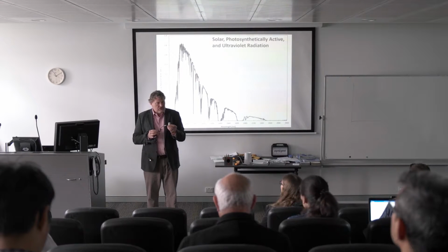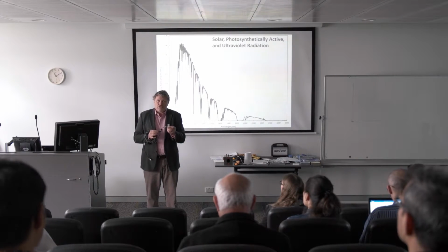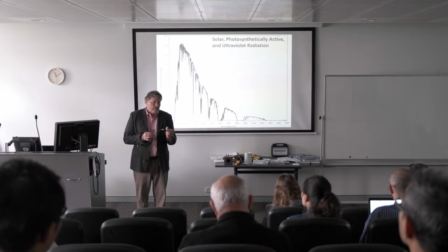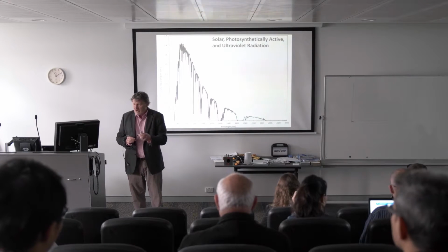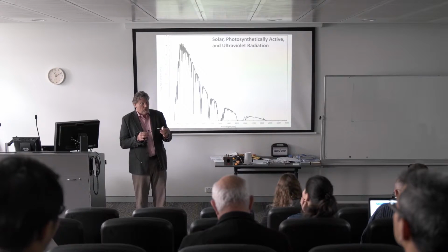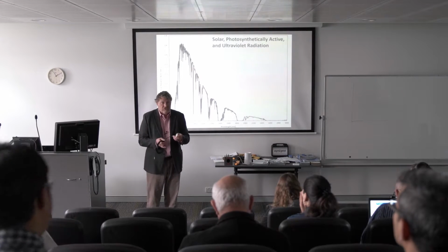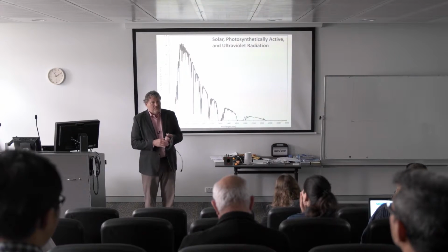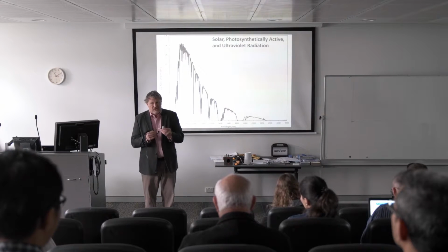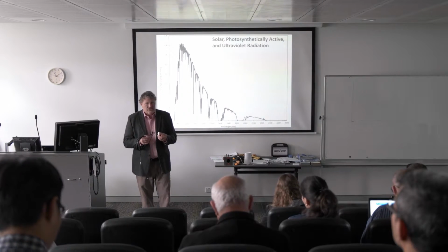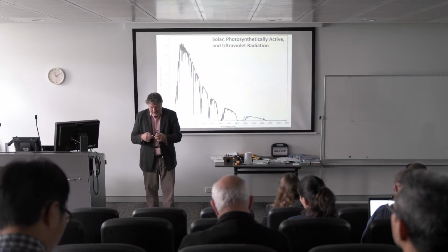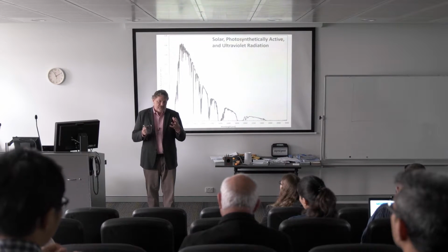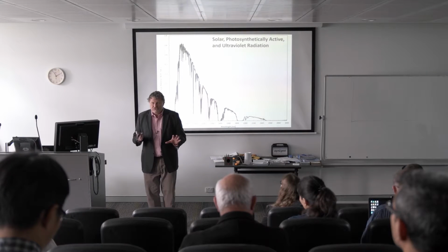And now silicon cell pyranometers are almost an order of magnitude cheaper than black body pyranometers. So all of us use silicon cell pyranometers on weather stations to get solar radiation for our Penman-Monteith models and everything else. And we just say, great, we've just saved a lot of money. But what I want to show you is the differences and the errors that you get with silicon cell pyranometers. And these are not widely appreciated. It's only our work comparing them rigorously back and forth that we've seen these things.